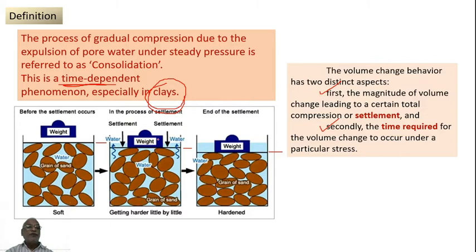Means when you put the load, as I told you, if the soil is clay soil, it will be taking a lot of time. Now how much is that time required for the settlement, and how much settlement is happening, whether it is a few millimeters or a few centimeters, that is the point of consideration.